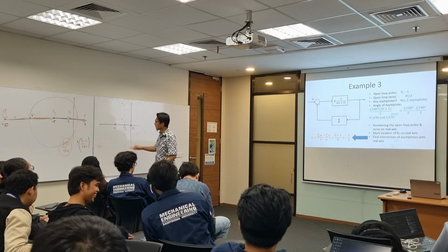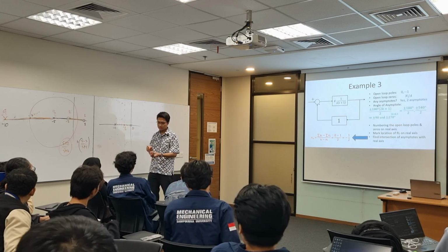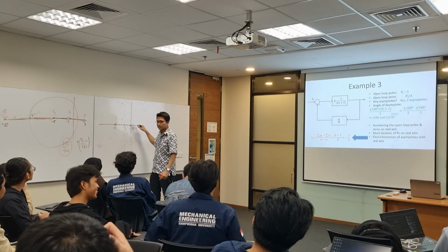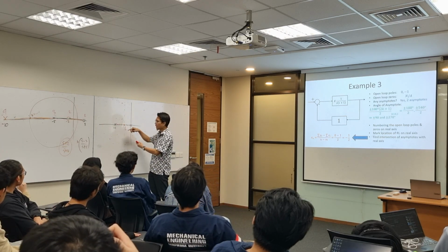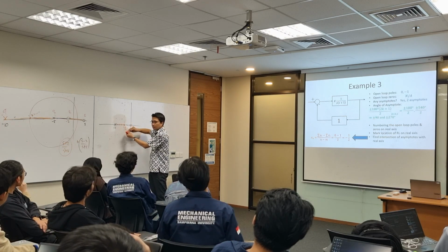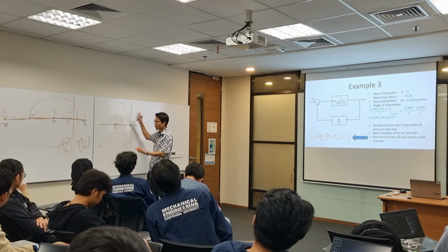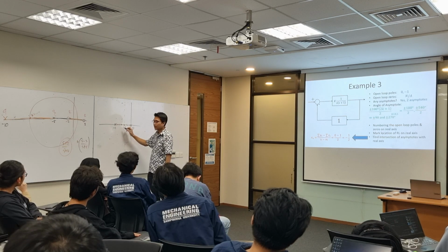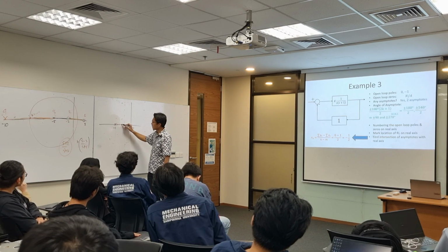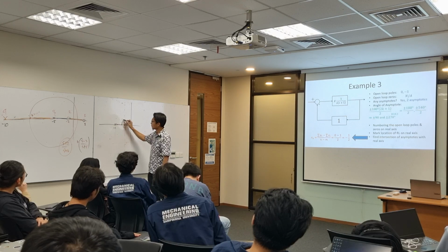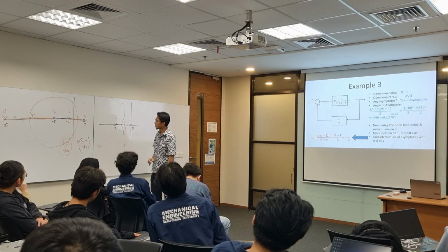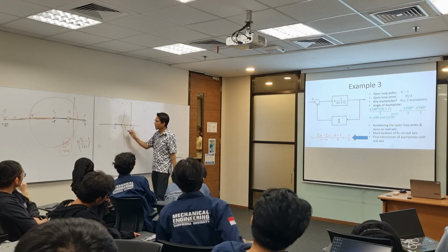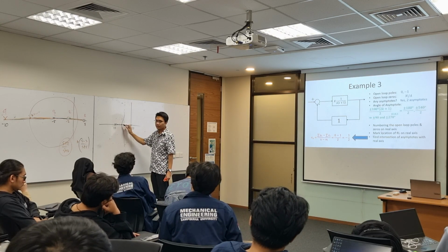Now this is just an intersection, yeah. But we know that on the real axis, these are our root locus, yeah. The next question is how does the root locus go into the asymptote? Where do these two root locus break or depart? Yeah. Let's say if it is from here, yeah, the departure point is from here. Then what will happen is that we'll go here, go like that. Okay. If this is the location of where they break away, we need to find out what is the location of breakaway.